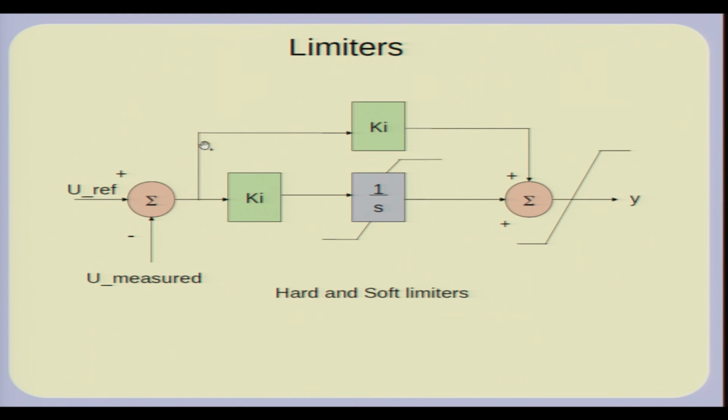So, a proportional controller, to get an output which is non-zero, it has to have a small error. Well, small or big depends on this gain. So, for example, in an excitation system, if you want to get say 2 per unit or a certain value of excitation voltage to achieve a certain UREF, you will have a small error. Okay. So, U measured will never be exactly equal to UREF if you have got a proportional controller.